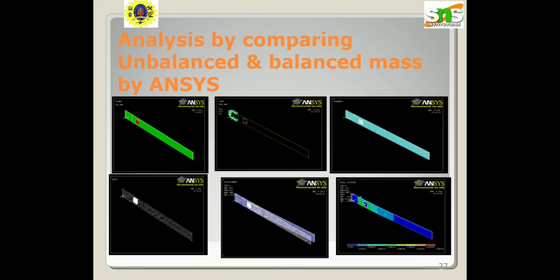The tuned parameter of the tuned mass damper enables the auxiliary mass to oscillate with a phase shift with respect to the motion of the structure. In a typical configuration, an auxiliary mass hung below the nacelle of a wind turbine is supported by dampers or friction plates. So, unwanted vibration may be caused by environmental forces on structures such as wind and earthquake, with a focus on vibration.